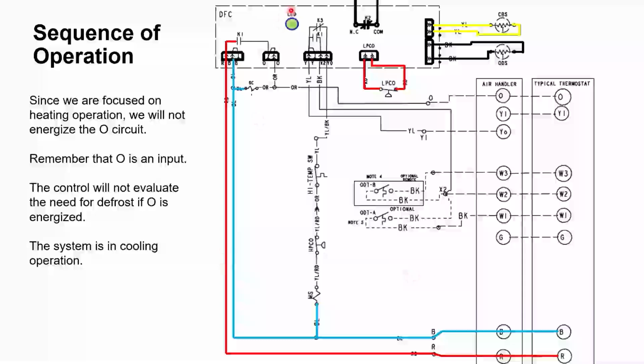And by the way, before I move on real quick, the outdoor temp sensor is the black wires, and if you notice on the board, it looks like the pins are set far apart. That's actually accurate. This is a 3-pin connector, but the center pin is missing. On the CTS, it's a 2-pin connector, so you cannot get them swapped.